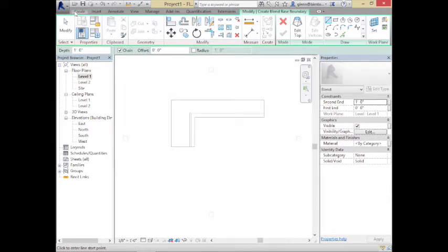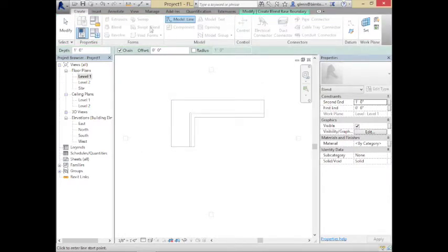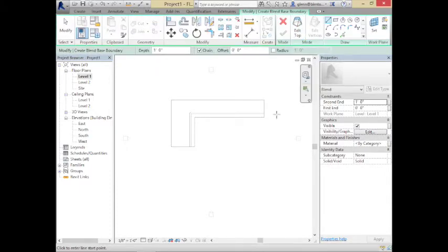Once you come to the Create tool, and you've already clicked on the Blend option, the first thing you do is edit the top footprint. You could draw anything you want. Let's say we're trying to do something like this, but with a square at the top. So you're going to edit the bottom first, and then click that button to switch to editing the top. So what we're doing is editing the bottom first, and then I'm going to click the top once you edit the top. Okay, so we did the footprint for that. Let's make it a circle.